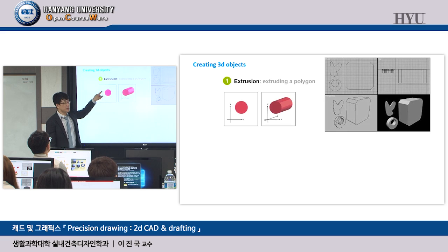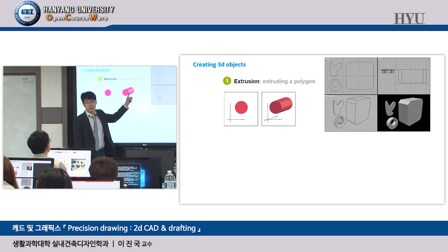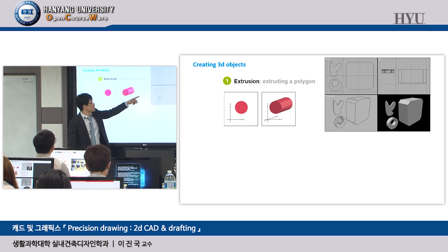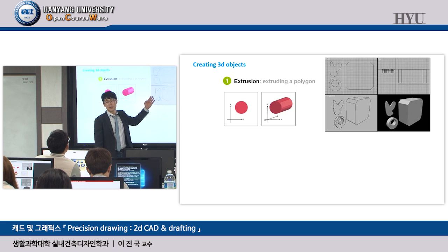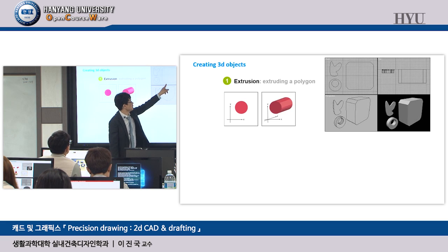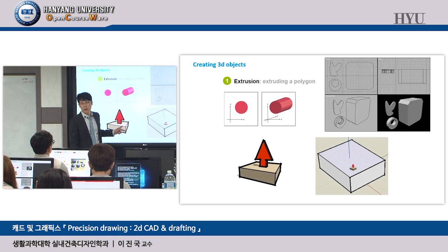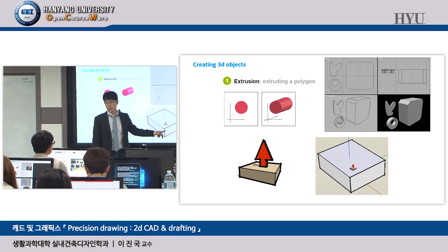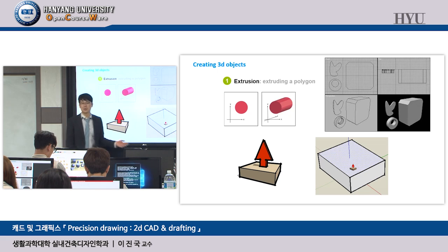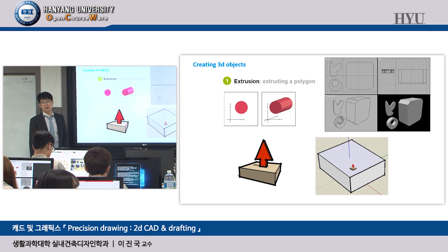Take a look, X, Y in the 2D section and the Z direction. That's extrusion, okay? This is the SketchUp interface, the 3D Max interface. Draw something and extrude with specific height, specific thickness numbers. How about in SketchUp? You know what this tool is, okay? Push-pull. By using push-pull, you can make some 3D using specific numbers. You can type millimeters, centimeters, meters, whatever. This is the easiest and the fundamental way of creating 3D.